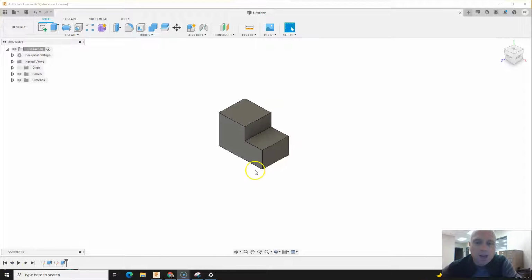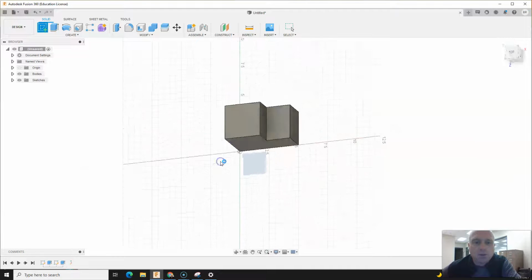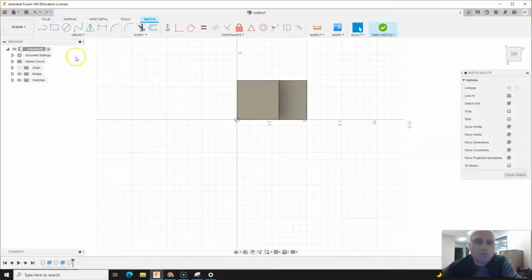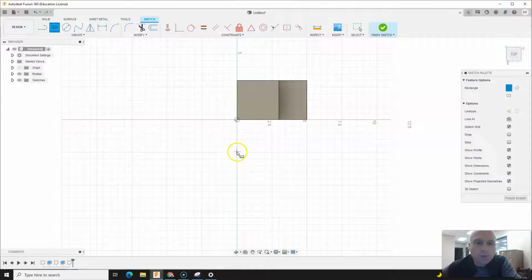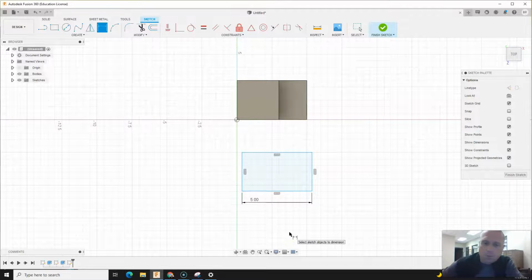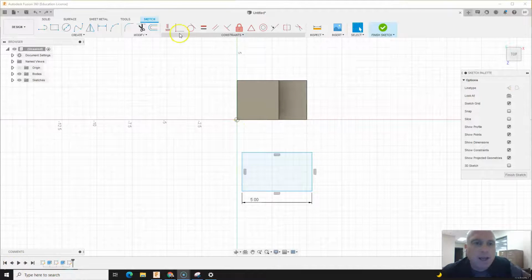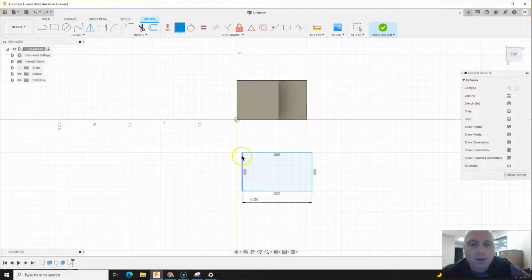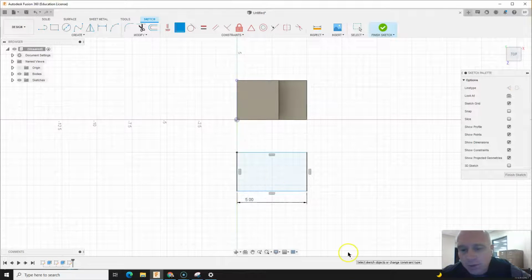Next, I'm going to show you a subtractive method for creating parts. And so again, I'll go ahead and click to create a sketch. I'm going to click this base work plane again. And I'm going to work down here in my sketch area. I'm going to draw a rectangle. I'll dimension that rectangle. It's going to have an overall width here of 5 inches. Then I'll add a coincident constraint to that, and I'm going to say that I want this point to always stay in line with that line, and that will move my sketch over.